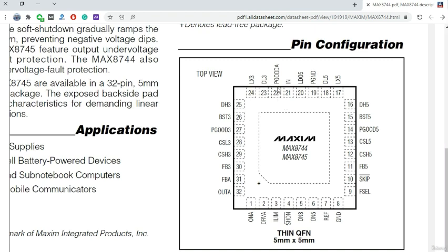So here we have the power good A, and drive low 3. Drive low 3 is the control signal for the low MOSFET of the 3 volt. Here we have LX3, which is the feedback telling whether the 3.3 volt is generated or not. Here we have drive high 3, the control signal for the high MOSFET in the 3.3 volt circuit.